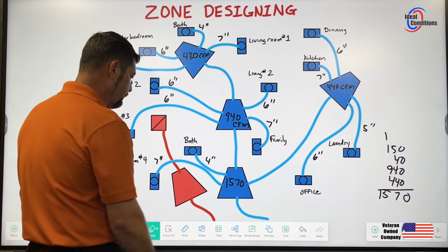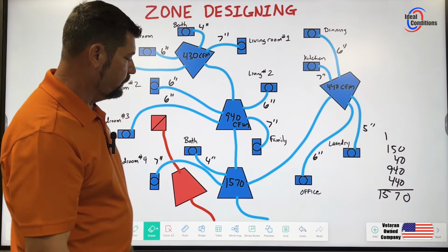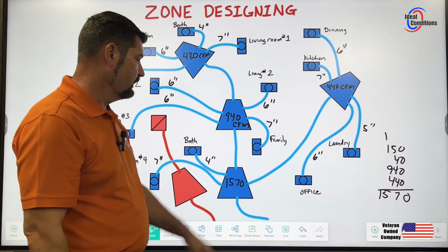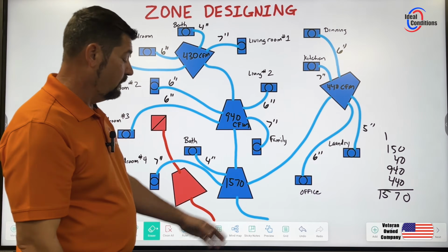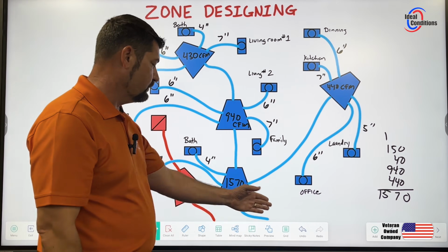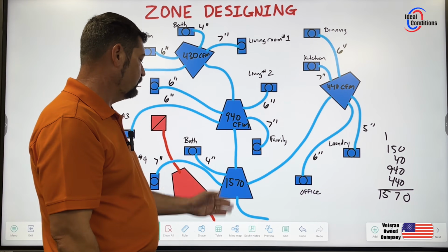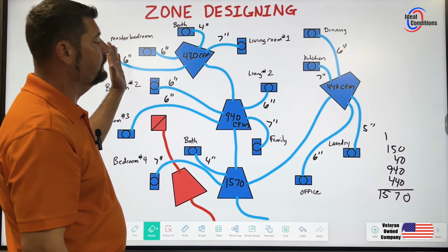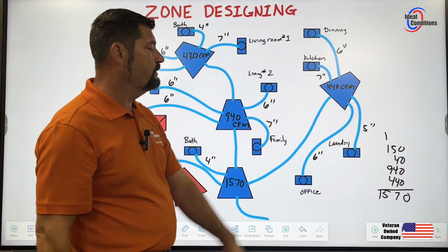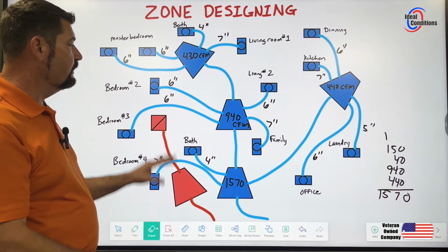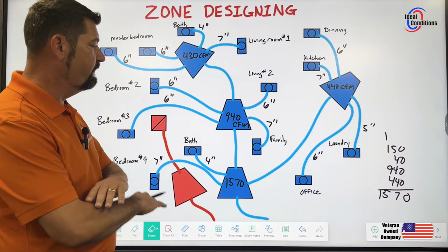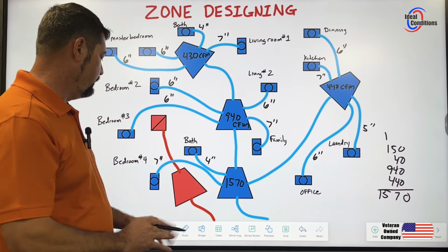So the value of this box is 1,517 CFM. So I hope that I have a 4-ton piece of equipment working on all that, because if I had smaller than 4-ton, like if I had a 3.5-ton, which is 1,400 CFMs, or if I had a 3-ton system that was putting out 1,200 CFMs, then this would be oversized. So that's why it's very important before you get started to find out what do you have. Because if you're going to be there fixing it, this is the time to take care of anything that's oversized and fix it all. You owe that.